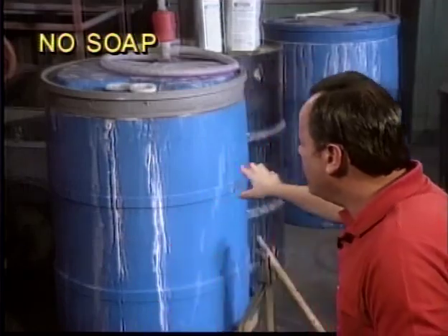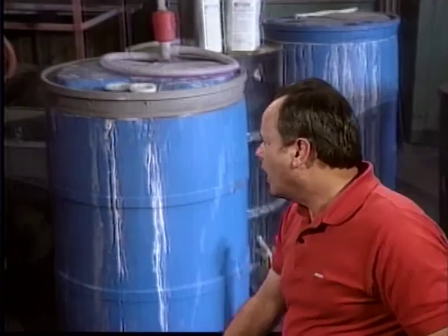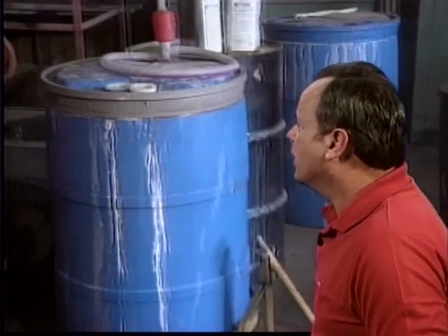Now, what else can you do wrong when you're cleaning engine parts? You can do a lot of things wrong, but one of them is using water-mixed degreasers. During overhaul, the disassembled parts of an engine are usually degreased with some form of mineral spirits rather than water-mixed degreasers, primarily because the water-mixed degreaser residues may cause engine oil contamination in the overhauled engine. So avoid soap and avoid water-mixed degreasers.